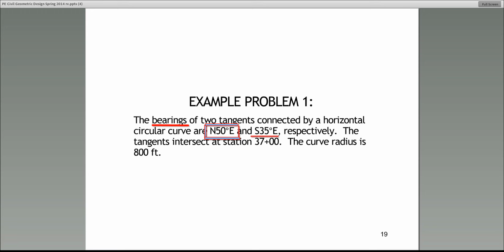By the way, I have to tell you, in these horizontal curve problems, when the surveyor designs a circular curve, more than likely the design parameter is either the radius or the degree of curvature, D. So the surveyor designs a curve based on what she decides the radius should be or the degree of curvature, and all these other parameters that we've talked about are calculated based on the assumed radius or the assumed degree of curvature. All right. Now let's get back to this problem.